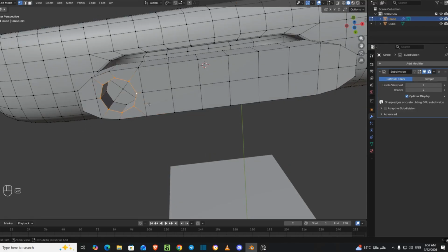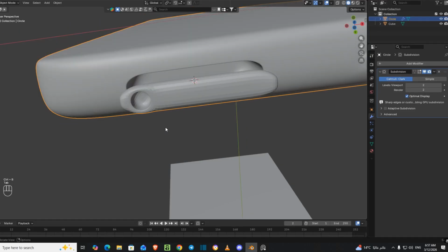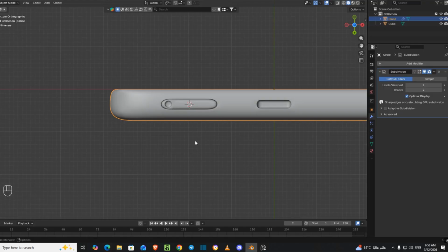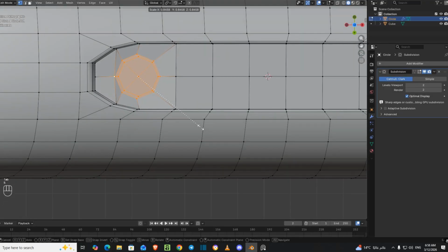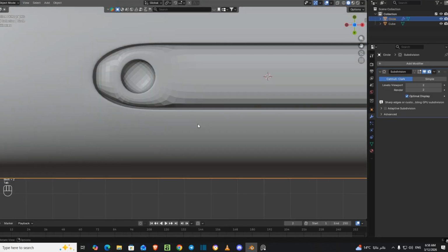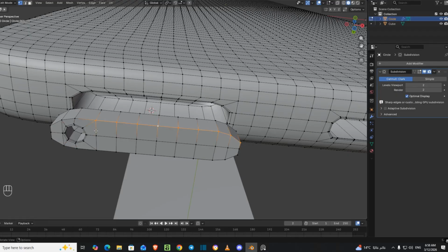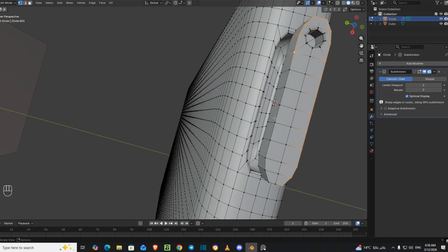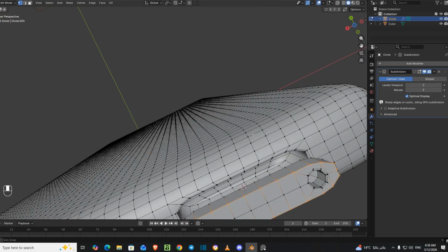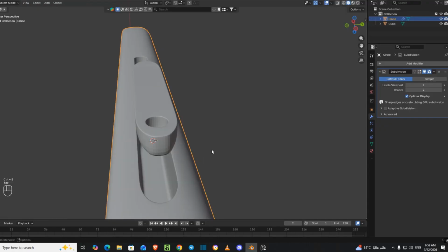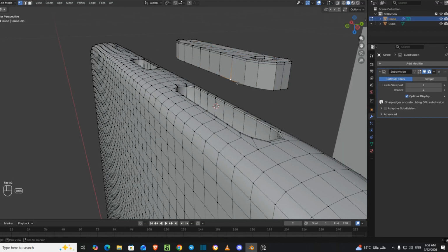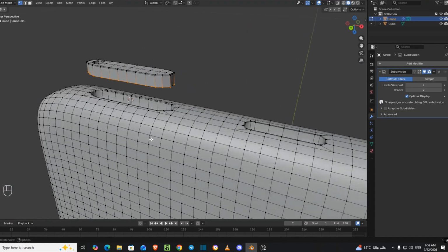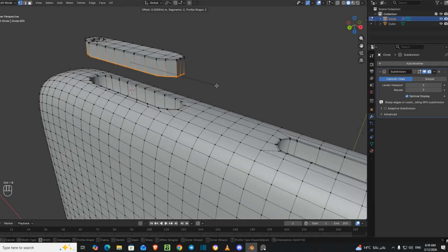Select this, but bevel. Select this one too and just move it without proportional editing. Needs to get a little bit smaller, along the X and Y axis only. Need to add bevel right here. Control B. Bevel of 2 in the shape of 1. Do the same for the lower part. Control B.